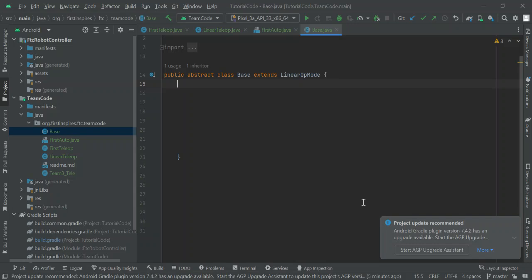The only problem is that sometimes it can be slow, and oftentimes you see the problem especially in arms, where you really need to tune. Run to position works on a PID, and the problem is it's a badly tuned PID because it's not tuned for your system. The value is already set by the SDK. So when using an arm, you'll see problems where it goes to the position and just wobbles back and forth because the PID is not well tuned.